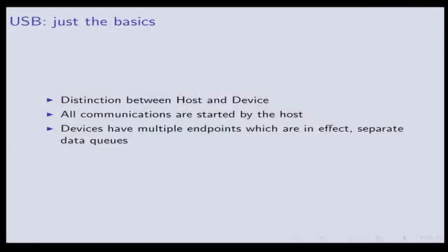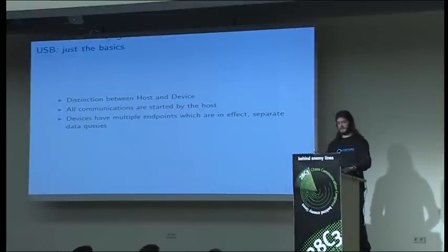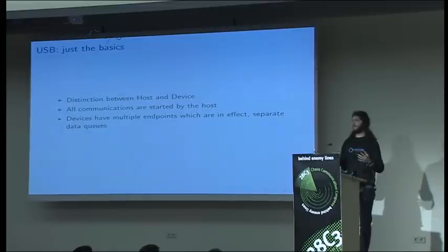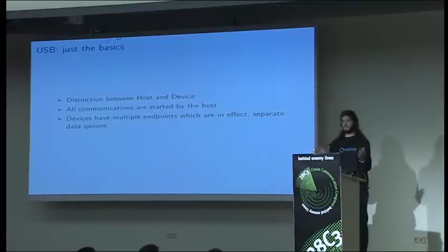So, USB. It's worth noting that the host and the device are separate concepts, and that the host is in charge of all communications. If the device wants to say something, it has to wait for the host to ask. You can tell which end of your cable is the host and the device because this end plugs into the host, and the one that's more blocky plugs into the device. Each device may have multiple configurations, and each device may have multiple endpoints, which are separate data streams.